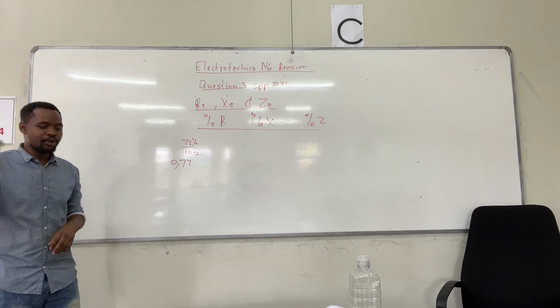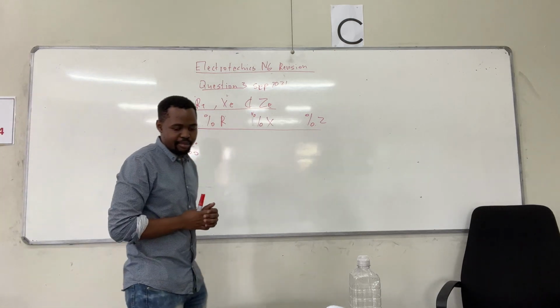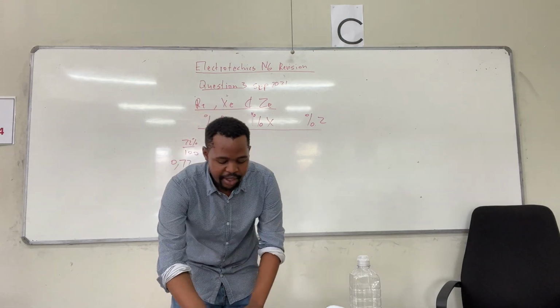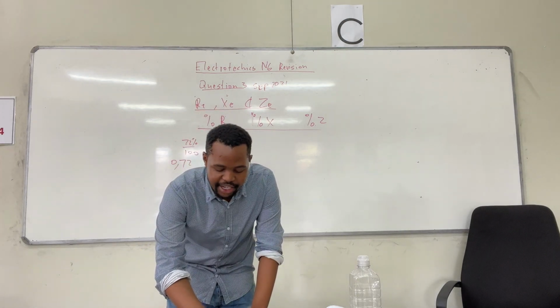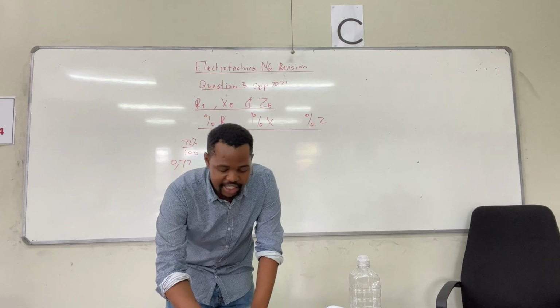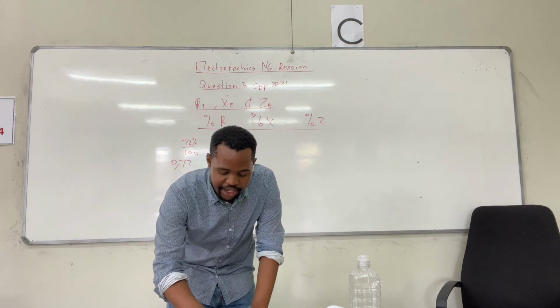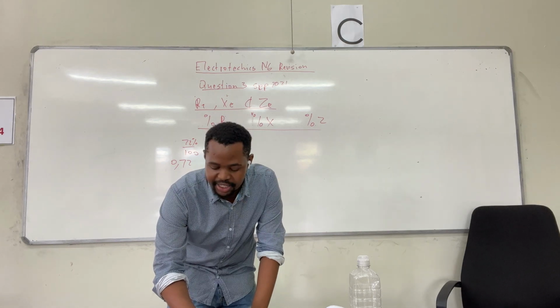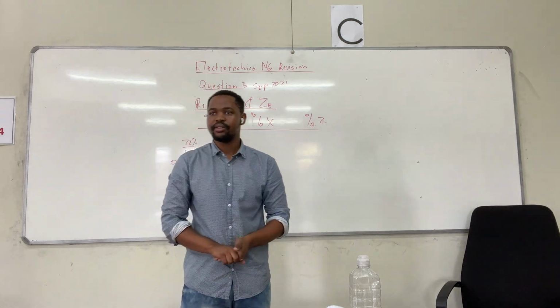So, guys, there are two reasons why the manufacturer does this. The first reason is that if the impedance is given in percentage or per unit form, we can use the same value on either side to calculate the equivalent resistance, reactance, and impedance in ohms.